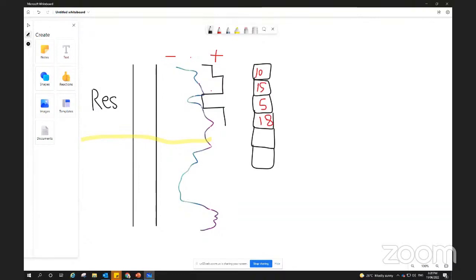Okay, reservoir engineers for upscaling. There's an upscaling process that the reservoir engineer does after the end of the static model. As I told you, they don't prefer the fine grid. They like the coarse grid. So there's a process in modeling software like Petrel, where you can take the whole grid with the whole properties and start dividing using multipliers.